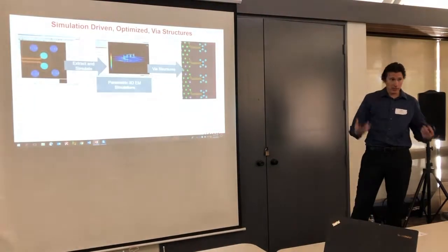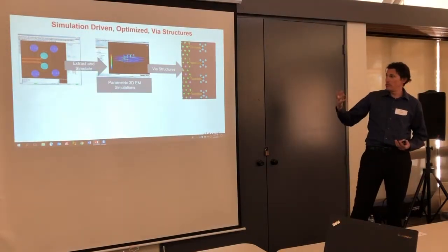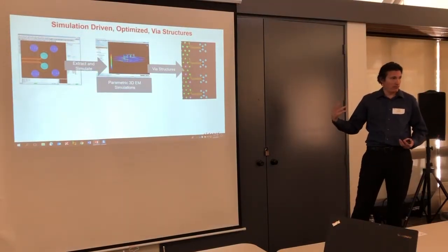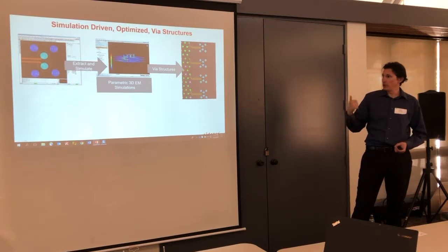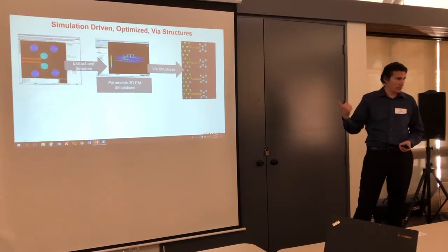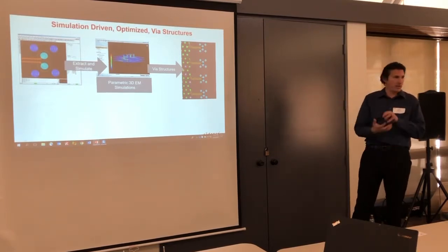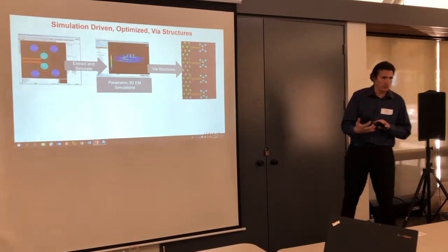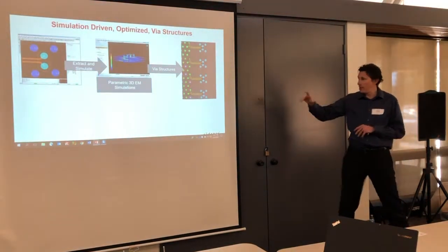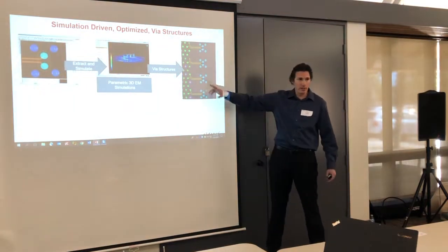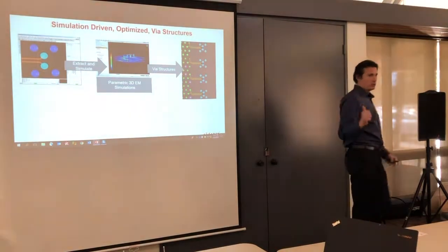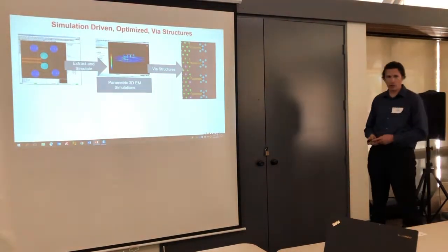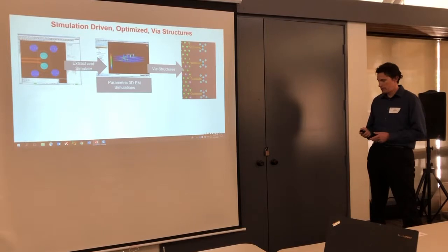And what we're seeing a lot of is it being a real simulation-driven type of via structure, right? Putting a ground via in is probably a good rule of thumb. Making it as close as possible, probably a good rule of thumb. But if you're lucky enough to have people in your organization with SI expertise, more than likely they're going to take your stackup and that differential pair signal and analyze the heck out of just a particular area. They're going to dial in exactly what the spacing and so on needs to be, and then give you that and say use this and only this and nothing else. That's ensuring that whatever is going on in that differential pair is going to hit the receiver correctly.